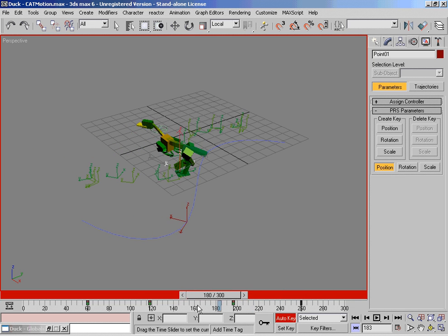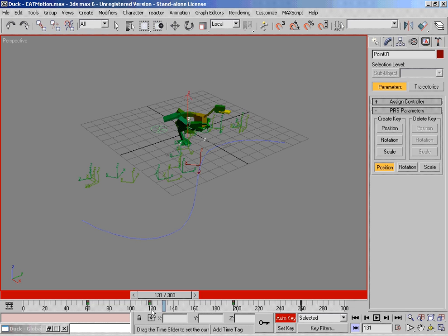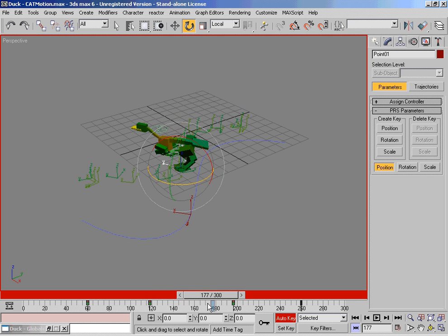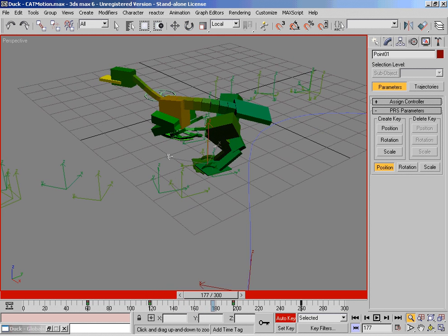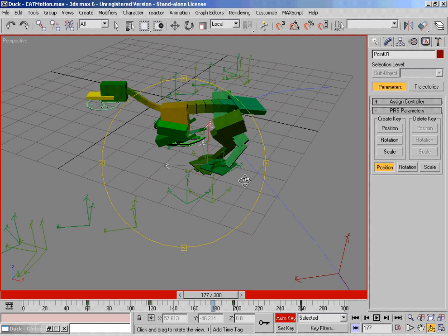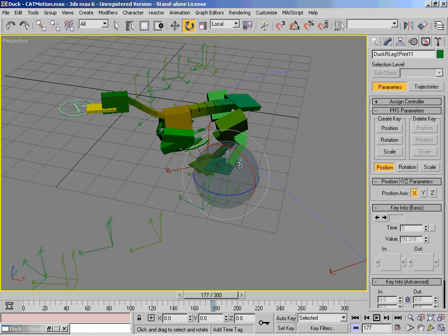This just illustrates how easy it is to work with CATMotion walk cycles and path nodes to create very complex walk cycles. One more thing is that we don't really do too much work to stop things like this happening, where the 2 feet cross over. However, it's very easy for the user just to zoom in, select the footprints, and adjust them to fix this problem.